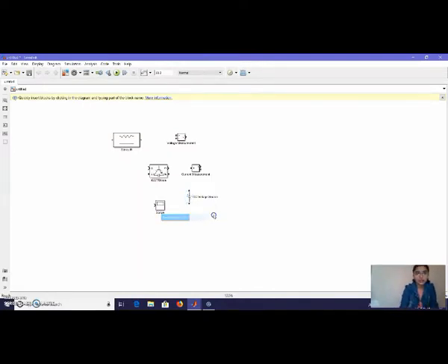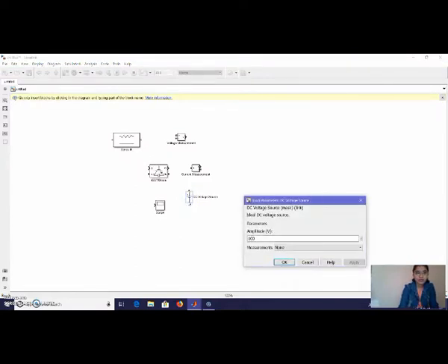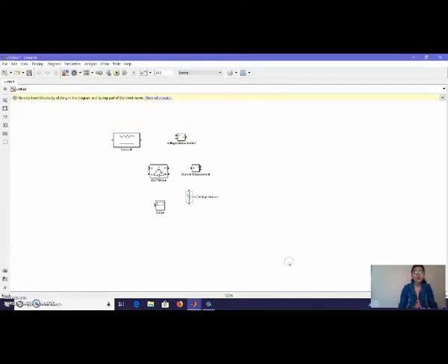So now double click on the DC source symbol. Now we need to change the voltage level to say 10. Here you can enter any values. Now make the number of channels 4. Also place Goto and From. Here you can change the name and copy and paste all the elements as we require multiple of these.